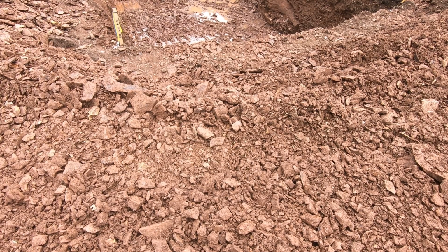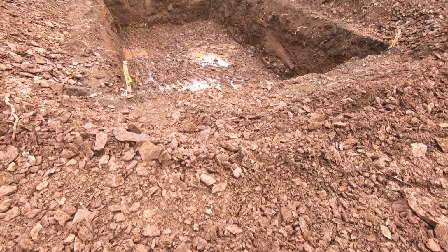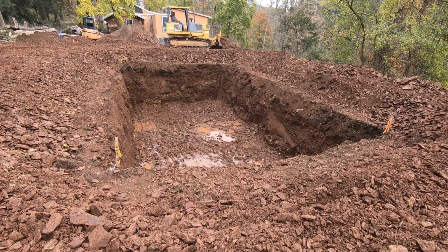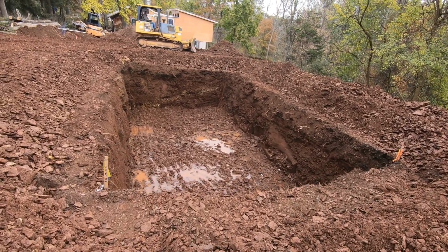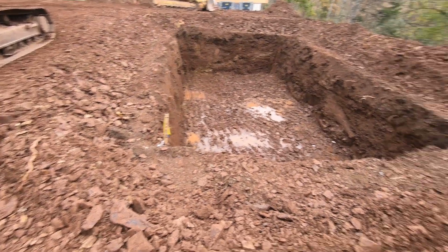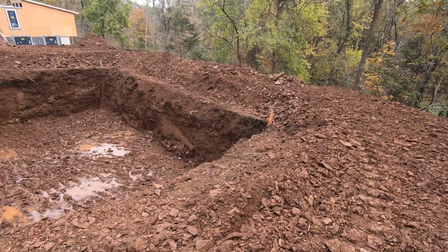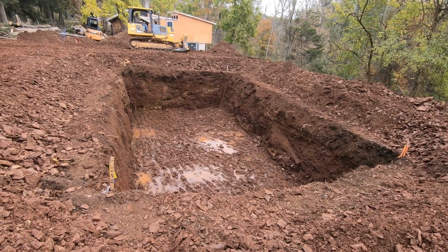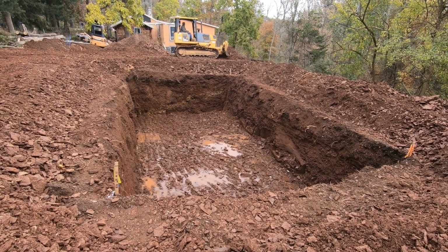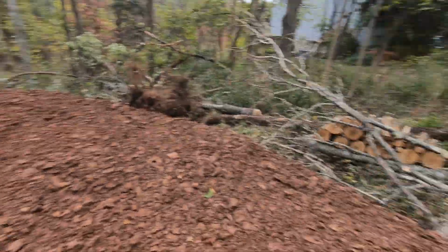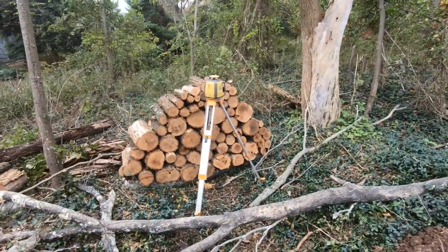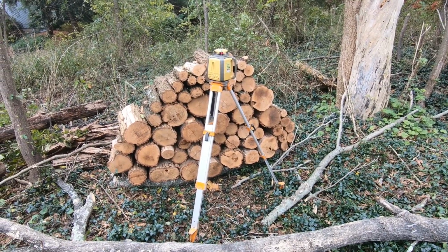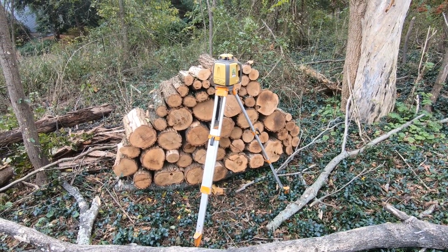All right, so this is what the open pit would look like for the septic system. You can see it's quite deep. You can see the stakes marking where the extents of the bed should go. Again, you can measure down to the bottom of the excavation with the tape measure, or this is the speed leveler, all right? So that attaches to the leveling rod and it'll let you know that it's at the bottom.